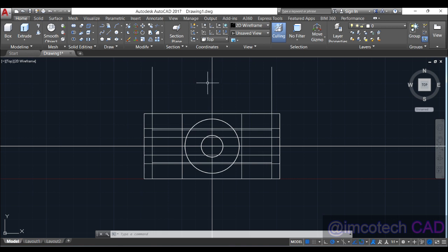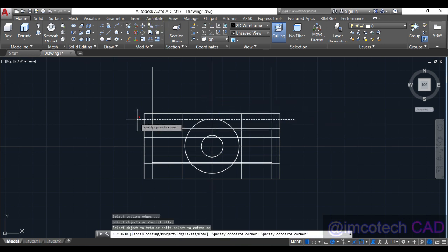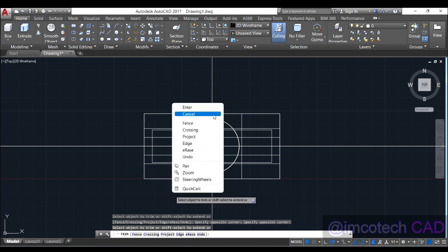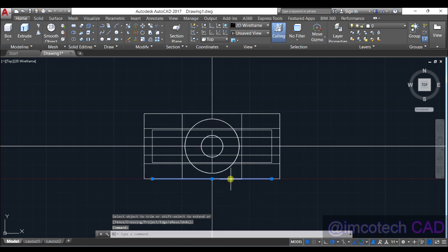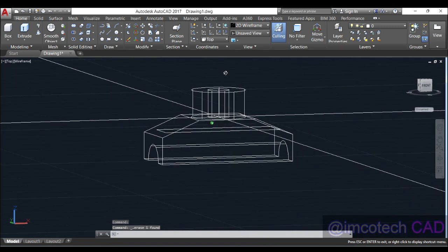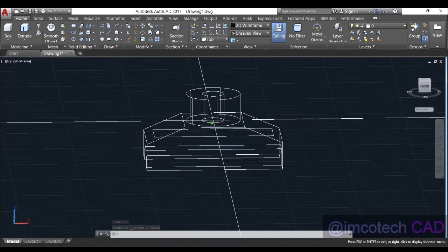So in drawing, most times they will not give you clear dimensions. We just give you dimensions that will enable you to make some calculations. Simple calculations, additions and subtraction for you to get the exact dimension. So we're going to trim now, and we will remove this part, and most probably delete this line here. Don't forget there's a line there. It's gone. Now we have the perfect shape in its position, and we're going to extrude that up.